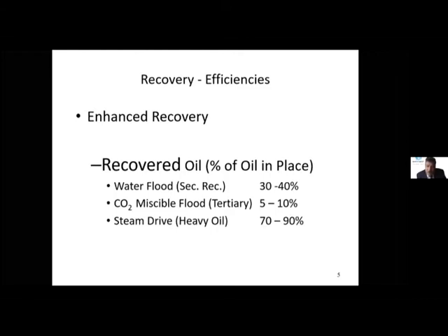Chemicals such as polymer and surfactant, and heat such as steam and sometimes hot water, all come under tertiary recovery. It depends on the oil as well: is it heavy or light? Is it high saturation or small saturation? But at the end of the day, you are recovering some percentage, but not all. You put a big project on water injection or water flooding, you spend good money on it, millions of dollars, but you will never ever recover all the oil.